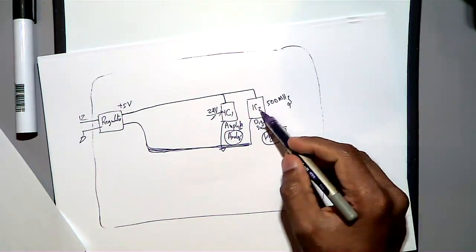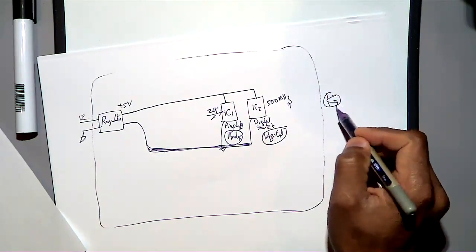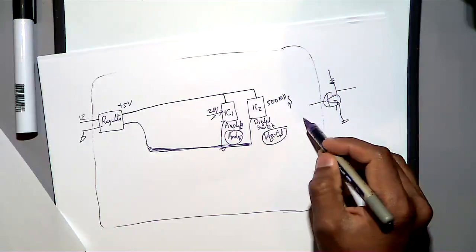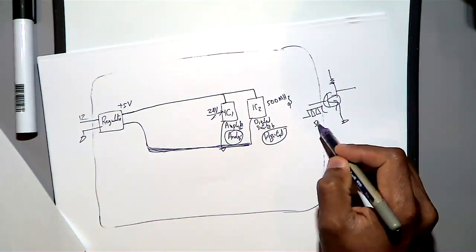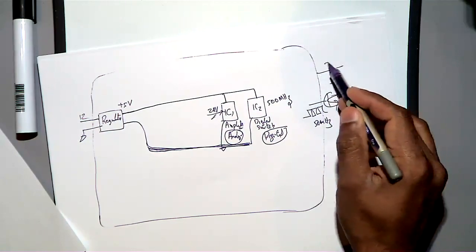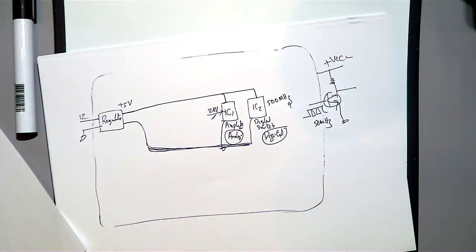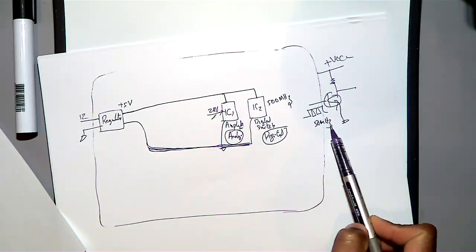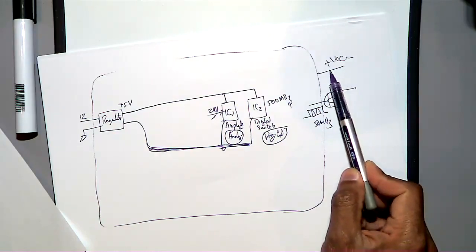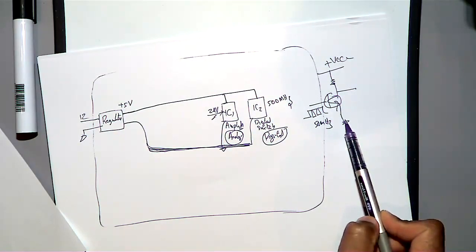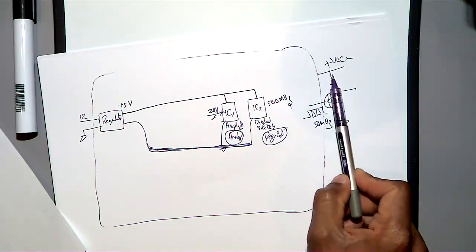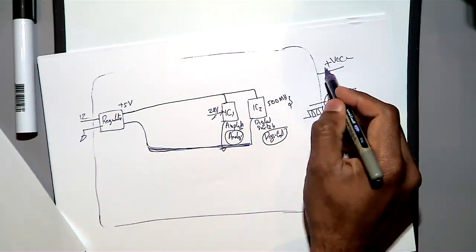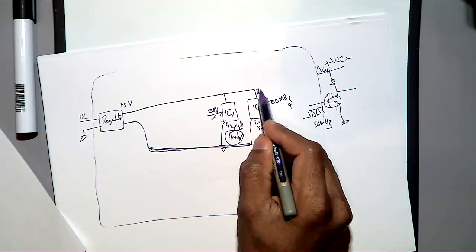Because when you look inside the digital IC, you have transistors, so many transistors, operating at 500 megahertz and connected to plus VCC. At 500 megahertz, this transistor is on and off at a very high frequency. You are drawing power when the transistor is on, and it stops when the transistor is off. Drawing, not drawing, drawing, not drawing, means you are generating a lot of noise here. So the digital IC will generate a lot of switching noise.